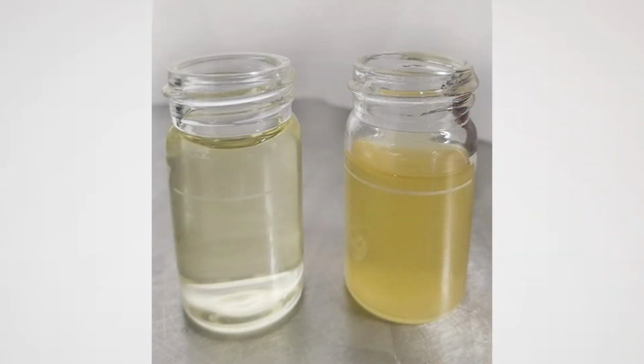Product loss translates to suspended solids. Suspended solids are measured by the dry weight of the solid material found in water. Some facilities get charged extra for a high level of suspended solids. Even if this charge doesn't apply, water with a high level of suspended solids generally also has a high BOD level, as the solids generally contribute to the oxygen demand.